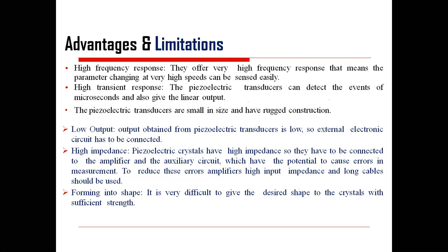However, when one side of the transducer has good things, there are some negative things also. So what are the negative things, limitations, or demerits of this piezoelectric crystal? It has a low output, so the output obtained from the piezoelectric transducer is low. So an external electronic circuit has to be connected for amplification of that signal, so that you can enhance it up to a certain limit as per the requirement of the application.